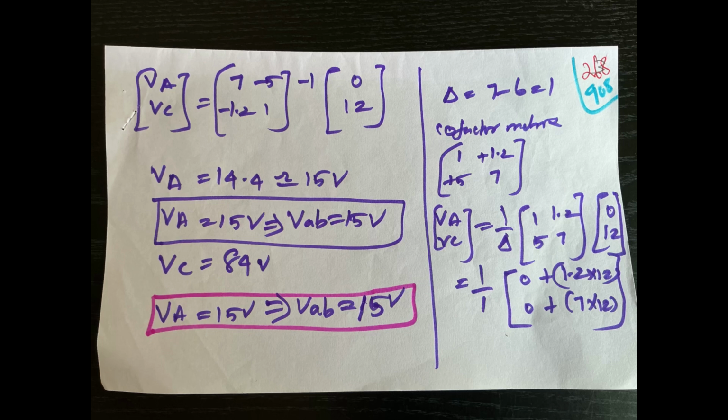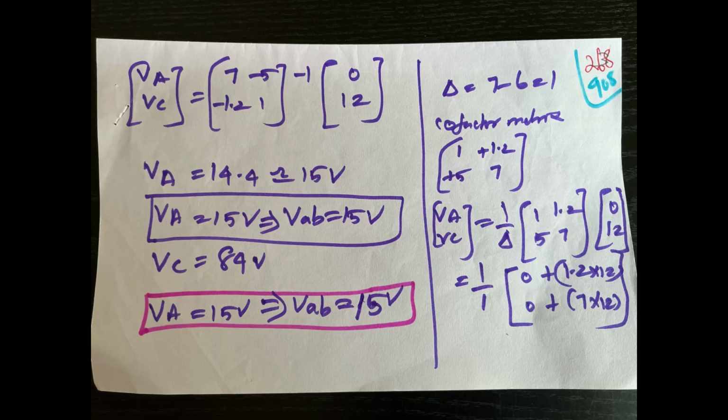VA value is the V Thevenin value, that is VAB, the open circuit voltage. I already explained the Thevenin steps. Remove the portion of the circuit across which the Thevenin equivalent circuit is to be found.